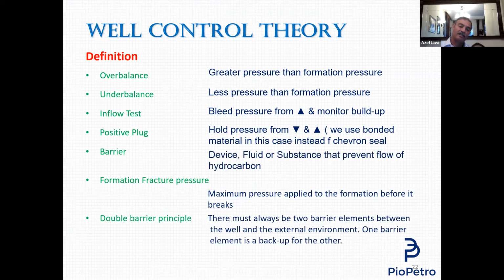Double barrier theory, this is something maybe I will go through quickly. The double barrier theory says that in the old days, when we used to pressure test, finish pressure test, run in hole, finish our job, and start pulling out of the hole, when we reach the surface, we go to the top valve on the Christmas tree, which we call the swab valve, and close the swab valve, preventing the hydrocarbons.